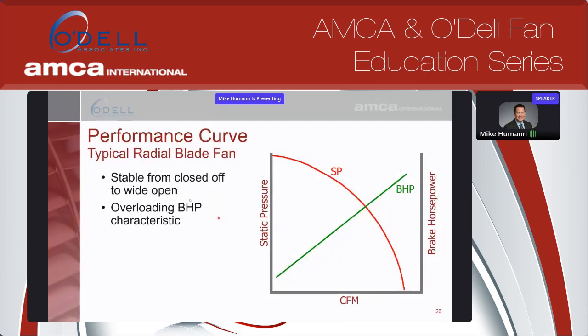So here's the radial blade fan performance curve. You can see here that with volume on the bottom, static pressure on the left, and brake horsepower on the right, when we're at zero flow, we're at our peak pressure. So this design is inherently stable from closed off with no flow all the way to wide open. But something to really consider here is this brake horsepower is ever increasing as your flow increases.